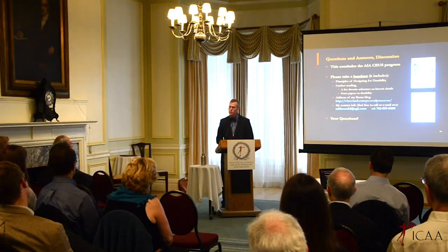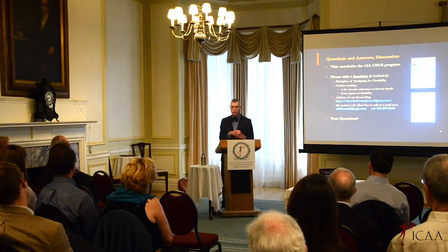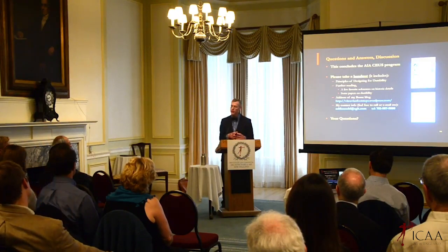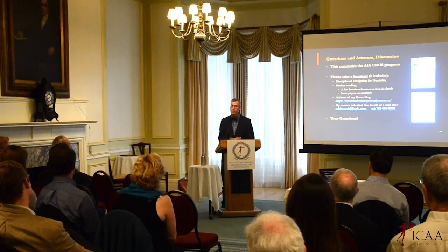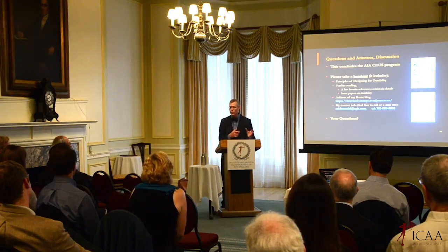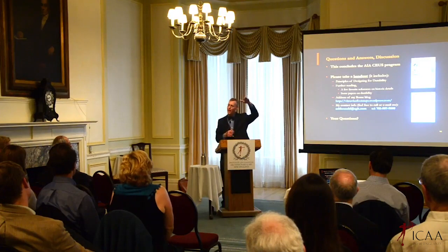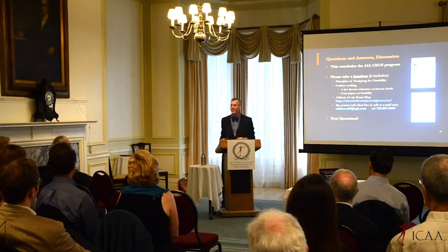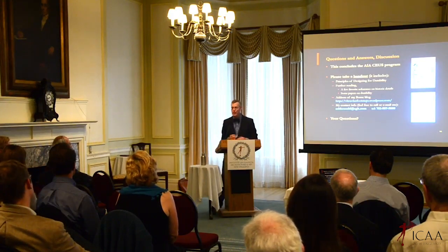It's not as obviously recognizable as contemporary concrete because they used very large aggregate. It's typically baseball, softball size aggregate. And sometimes they used chunks of stone for that, and sometimes chunks of brick. In the case of the Pantheon, there's a very clever design where the higher they got on the dome, the lighter the aggregate they used, to help deal with the structural forces on that dome. So they were using things like pumice, which is very light, for the aggregate higher up, and transitioning.